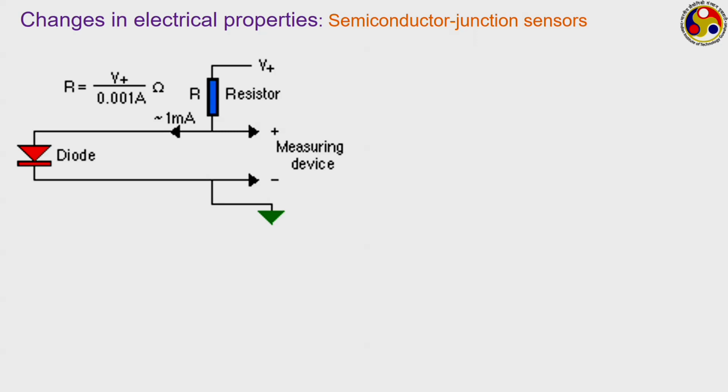As we know from your knowledge about physics, as the temperature changes, the performance of a diode also changes, both during forward bias and reverse bias, and the voltage output from a diode keeps on changing. Just the same principle is used. So, you can make use of a very simple diode, take it in contact with the surface where you want the temperature measurement, and by noting the corresponding change in voltage, which is generally very linear, we can easily get a measurement of the corresponding temperature of the surface.